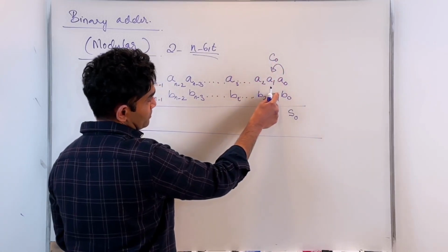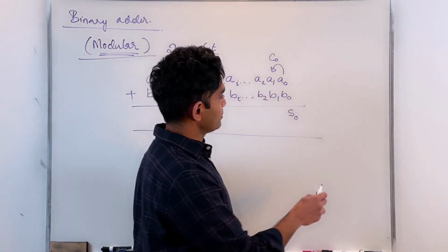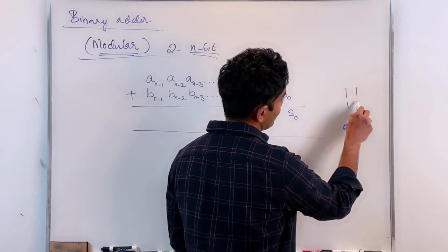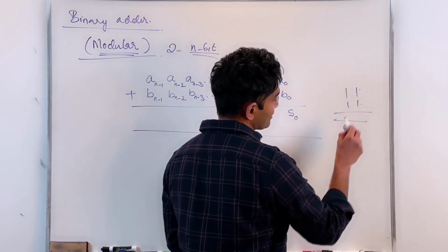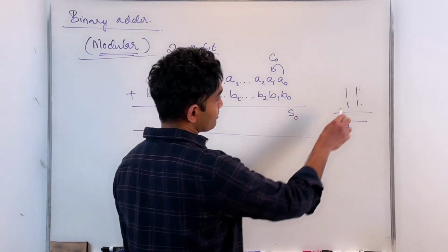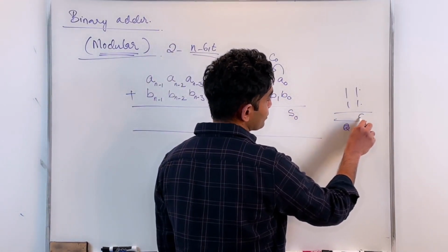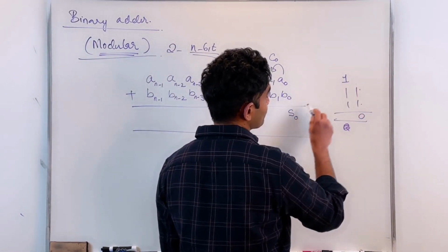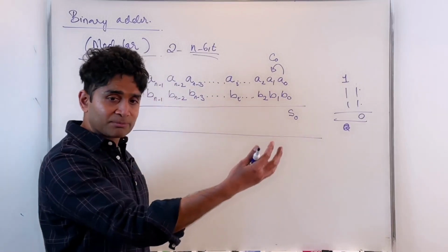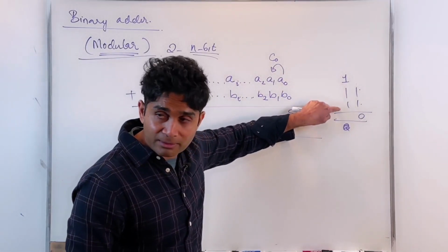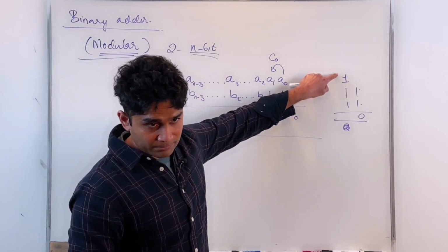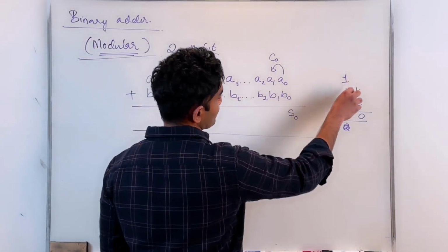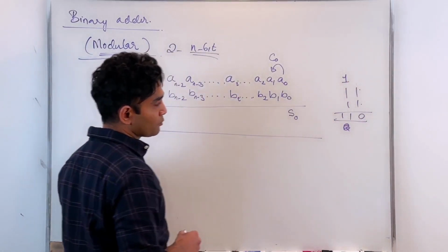to the next bit position. And that's how you do the addition operation. So let's say you have two binary numbers, 1 1 and 1 1. I start with the rightmost bit and add them together. 1 plus 1 is 1 0. So 0 gets left over here, and then I carry over the 1 to the next bit position. When I'm adding in the next bit position, I add the two individual bits together along with the carry out. That's the typical way we do addition. And that's 1 plus 1 plus 1 is 3, which is 1 1.